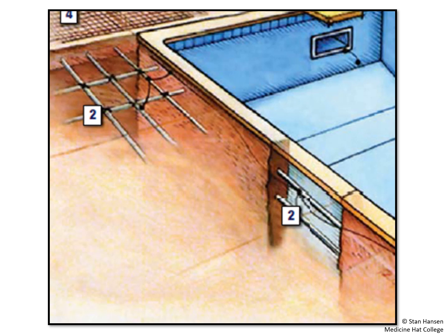Any of the pool reinforcing steel must be grounded in at least 4 locations that are evenly spaced around the pool, and this will include any reinforcement inside the pool deck itself. If the rebar the concrete installers are using has a non-conductive coating, then we must also install a number 6 copper conductor loop all the way around the pool, and that loop must be below the water level.